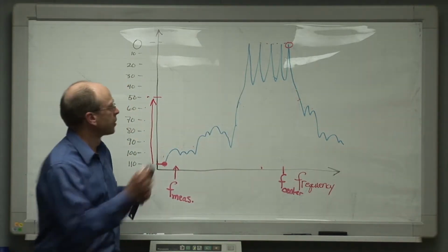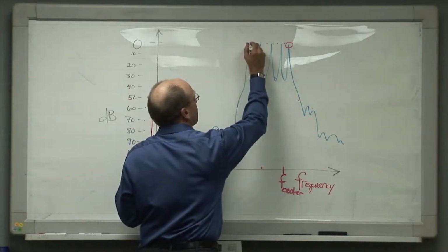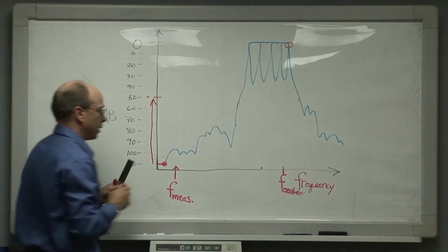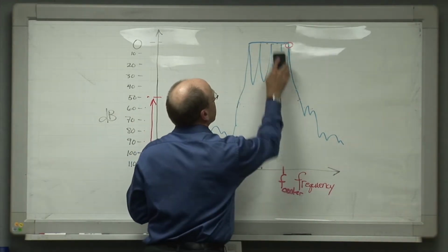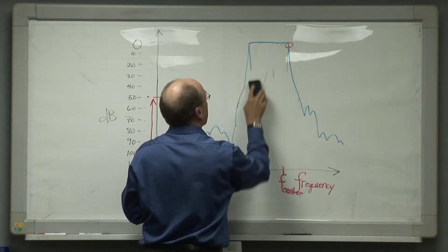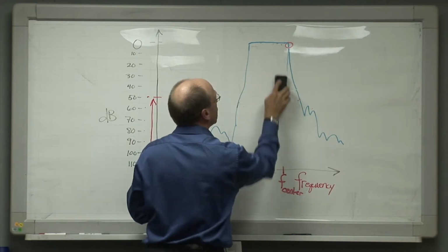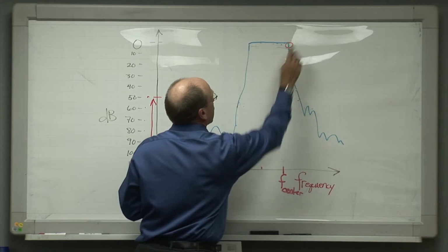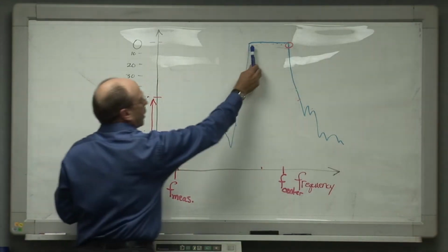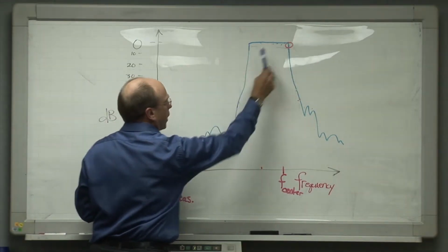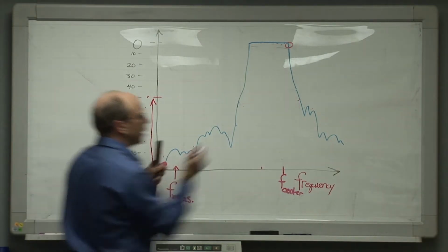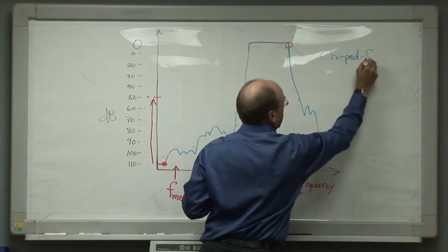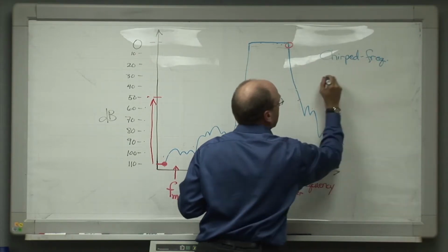Another thing that some radars do, and we talked about this also, is sometimes they will simply operate like that. They do not have a set of discrete frequencies in here. What these radars do is to, in fact, operate with continuous emission all the way across some portion of the spectrum. These are the so-called chirp frequency radars.